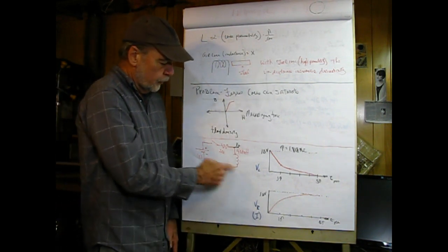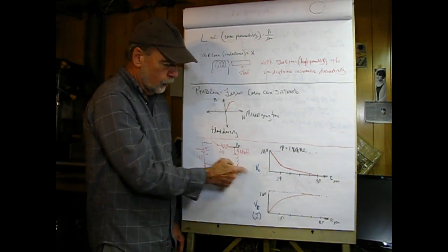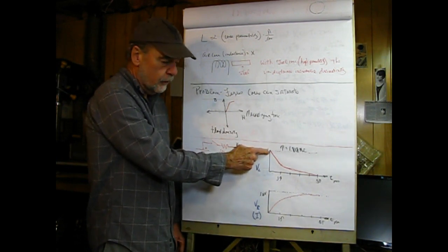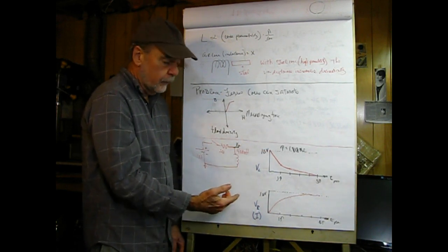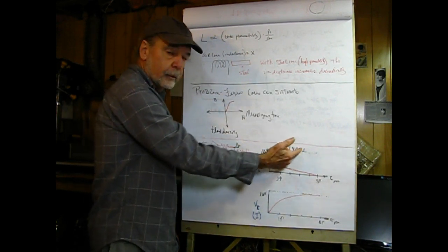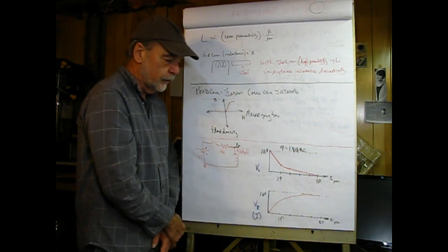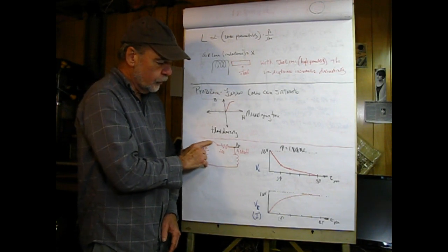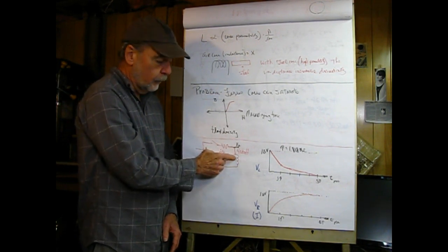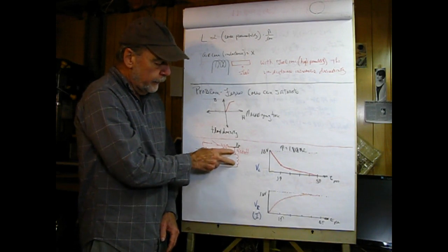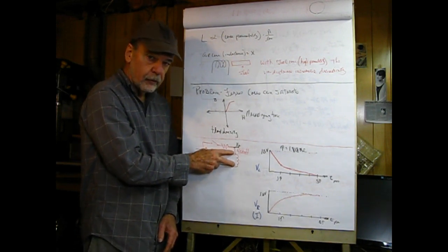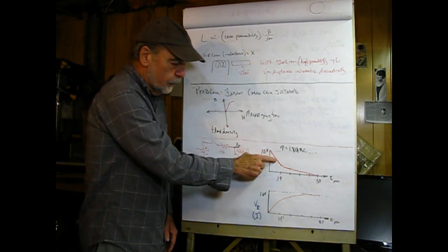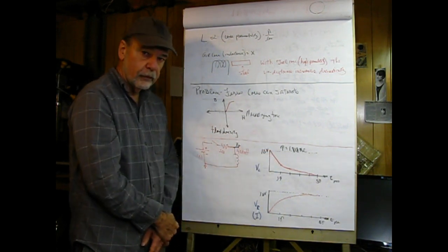So what happens here is that at t equals 0 plus the switch closes, and surprisingly the voltage across the inductor jumps up to the supply voltage, 10 volts. Now in a capacitor, if you recall, it started at 0 and began to increase asymptotically, approaching 10 volts. What's going on here is when you close the switch, current starts to flow, that magnetic field builds up, opposes the source, and all of the voltage at t equals 0 plus is across the inductor. And then as the current begins to flow, the voltage across the inductor decreases.